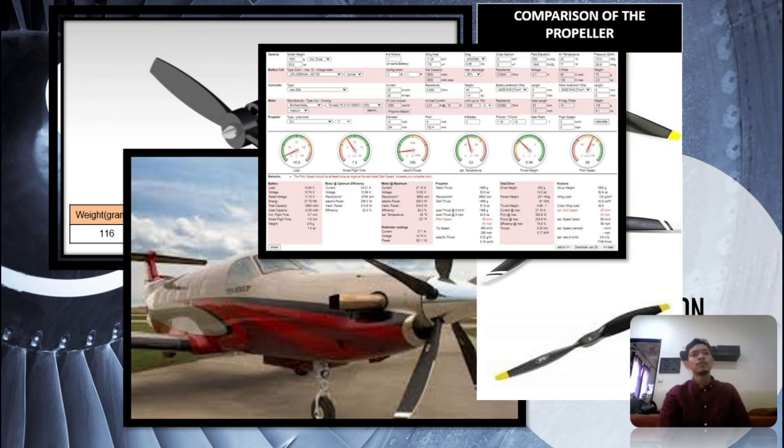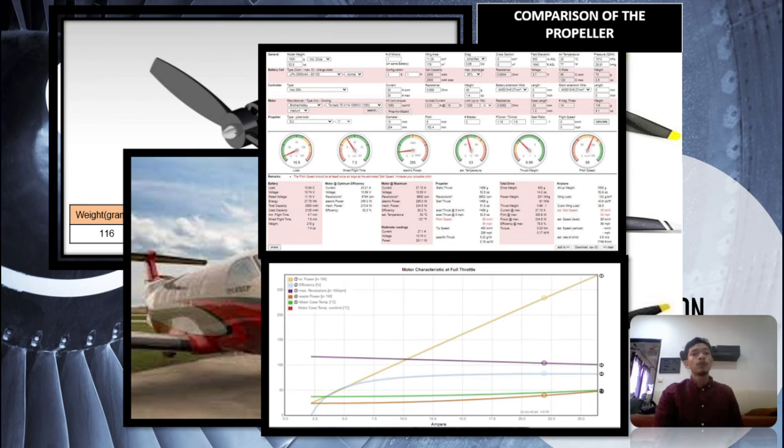The pitch speed should be at least twice as large as the estimated stall speed. The propeller will still develop some thrust at this speed, but not much. ECAL will predict great static thrust with a large diameter for low pitch with a low RPM propeller. But if the dynamic thrust drops off too fast, the model may be partially unflyable. So we proceed with the 2 blade propellers.